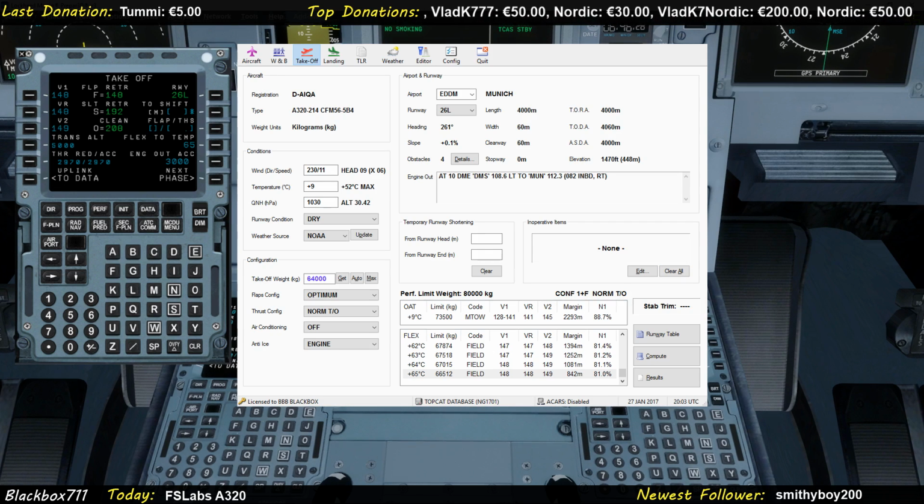Yes, for example in summertime, you can do two things. To make sure your passengers don't get unhappy with high temperatures building up when you switch off the air conditioning, either leave the air conditioning running, or if you need the performance, you can use APU bleed for the air conditioning. That way you still have the maximum thrust available to the engines. Okay, so flaps also one.